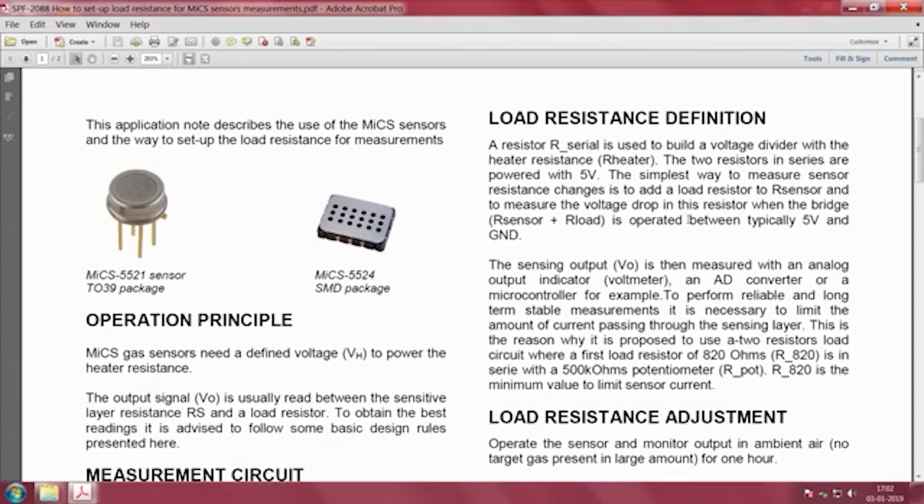please note that all efforts in semiconductor sensors are trying to get to the value of the change from the base. Change in what? Change in resistance from the base. So Rs by R0, where R0 is the value you have derived under normal circumstances, in clean air, in the absence of NO2.